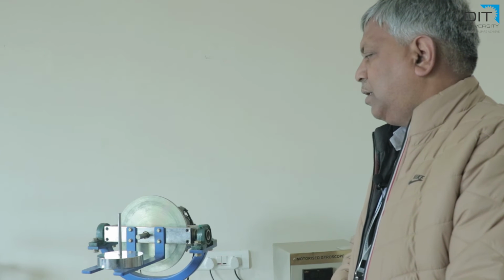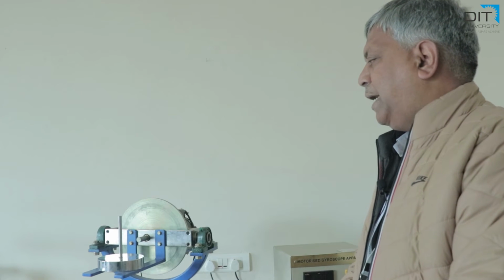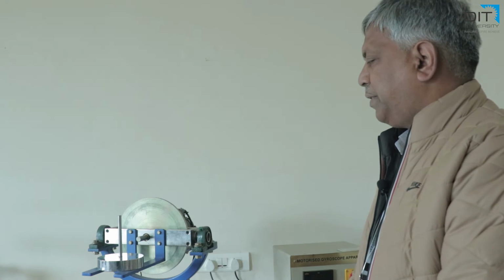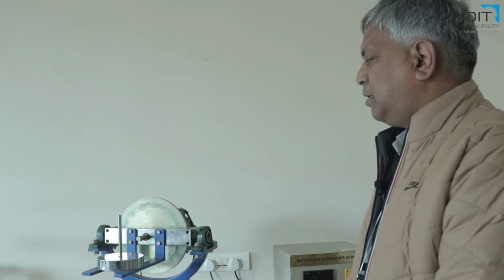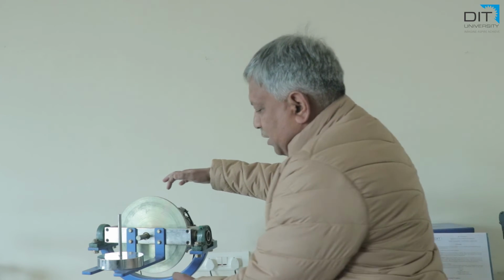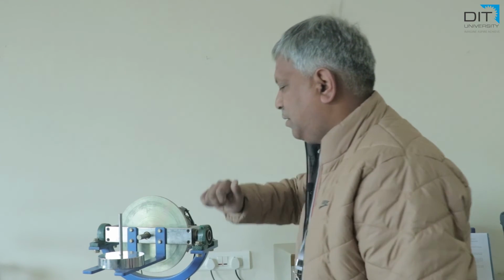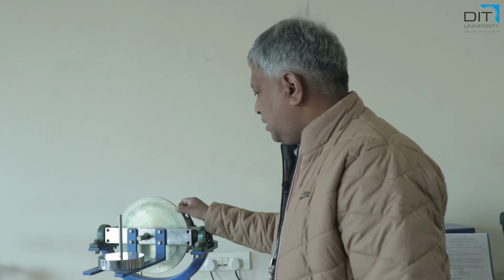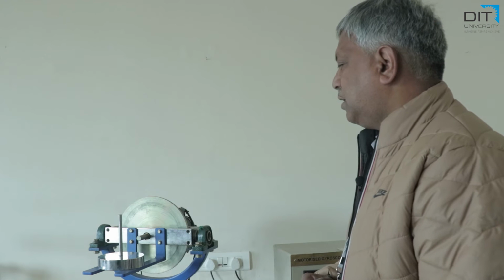It has been found that the weight of the disc comes as 4 kilogram, and if you want to measure the weight of the disc on this setup, it is not possible. Now how can we do it? For that, first of all, we will have to take the dimension of the disc, right? You can measure this with the vernier caliper. It comes as 250 millimeter. Then measure the thickness. It comes as 10 millimeter.